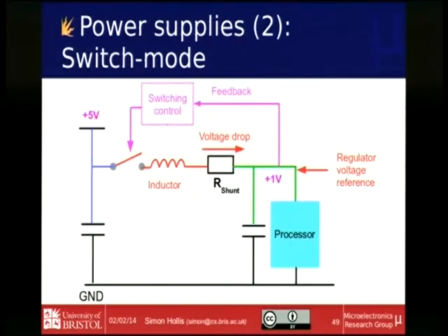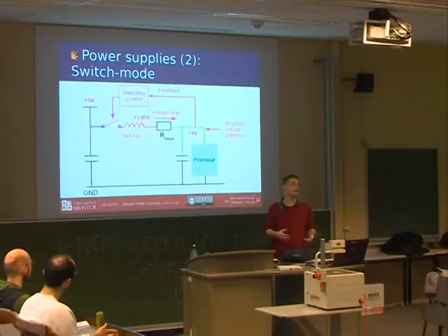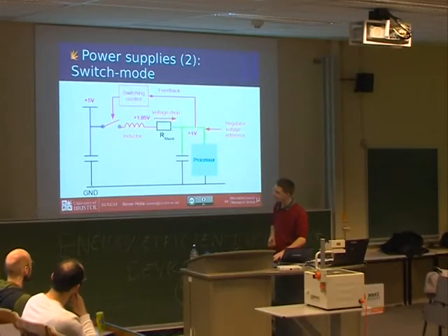It's 5 volts in. You'll get 1 volt out if it's a 1 volt power supply. And the reason is because the power supply will increment on the other side of the shunt resistor. Automatically it will adjust there. So the shunt resistor will be there, that would be 1 volt. Since it's there, it notices that the voltage changes across it. So now you can run your processor at 1 volt, which is potentially what you want to calculate. So it's better from the point of view of being able to make a more accurate measurement for the conditions that you want.